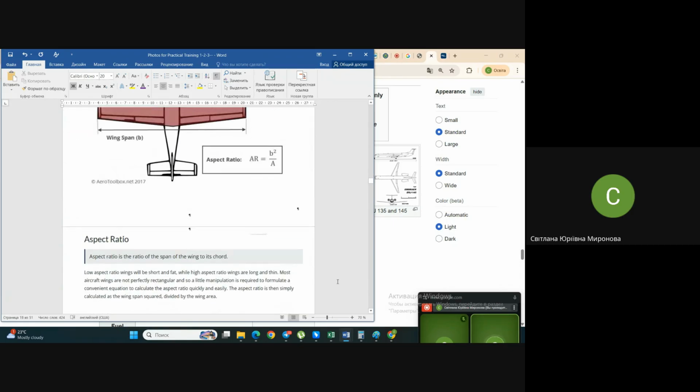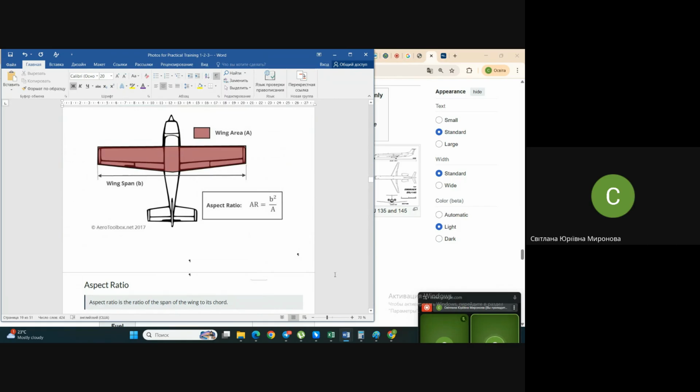Next is calculating the wing parameters like span and chord, having the area and some dimensionless parameters. You may do the same, if you don't mind, for the stabilizer and fin. Stabilizer and fin area you may not calculate because it's too complicated, and moreover, it's necessary to understand the distance between wing and stabilizer. At least for this, it's necessary to join them, to place them somewhere, to accommodate them somewhere on the fuselage. And first, it seems it's necessary to design the fuselage in this case.